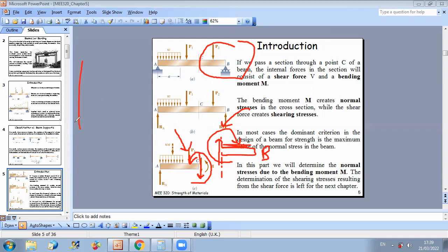If I want to draw shear and bending moment diagrams, whatever the section I do the analysis for, I get the same expression of V and M. So when I draw on a graph, I get exactly the same result if I do analysis on right parts or on left parts. This is why we make a convention and we follow it.